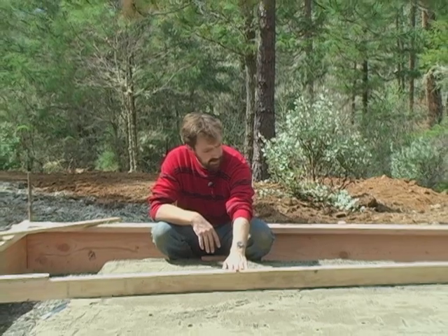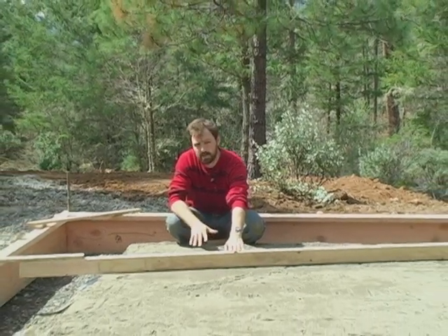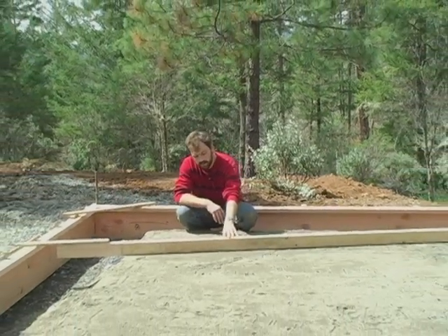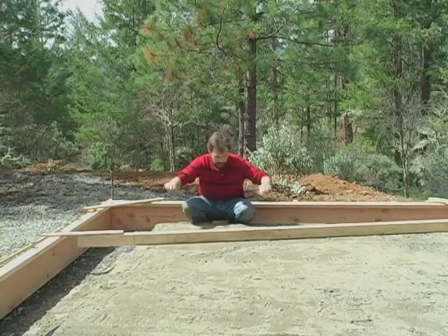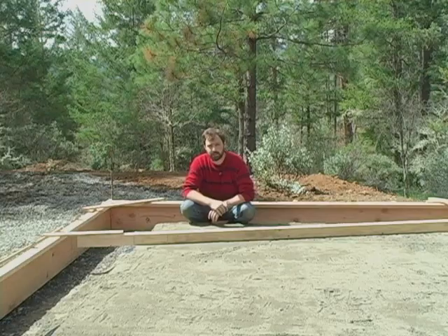I've gone ahead and used a screed board to get it level, which is its second purpose: it becomes a leveling bed. Now I know I want 3.5 inches of concrete, so I used a 2x4 here and just ran it as a screed board down the sides and got it completely flat and leveled off.